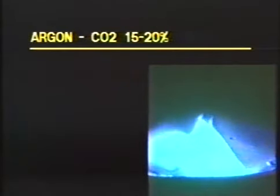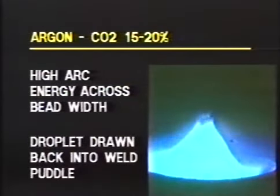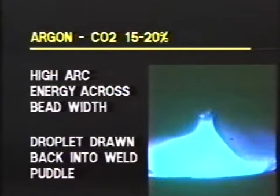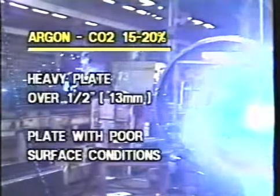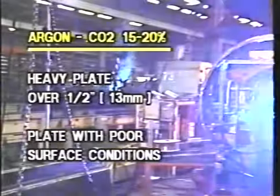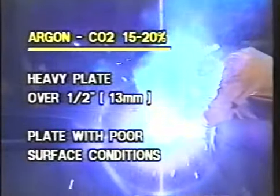15 to 20% CO2, in contrast to other argon mixes, provides high arc energy across the width of the weld bead. Note the way the droplets are drawn into the weld puddle, adding to the penetration. 15 to 20% CO2 is an ideal mix for spray transfer on heavy plate over 1/2 inch, which requires optimum penetration with minimum porosity. On plate with poor surface conditions, such as rust or mill scale, CO2 in this range provides improved arc stability.